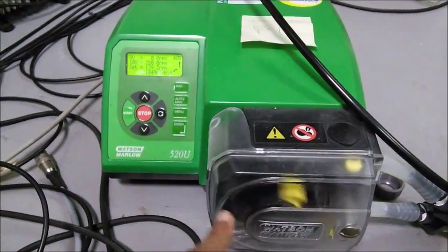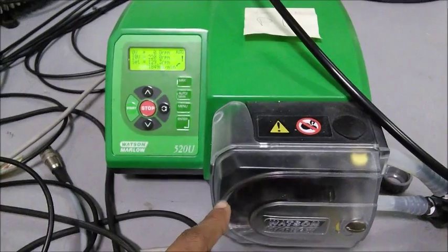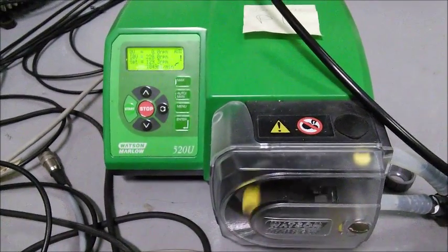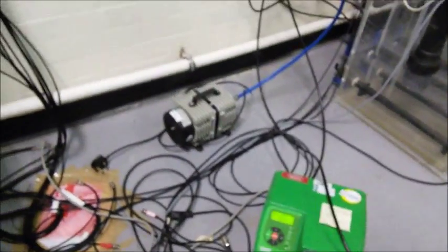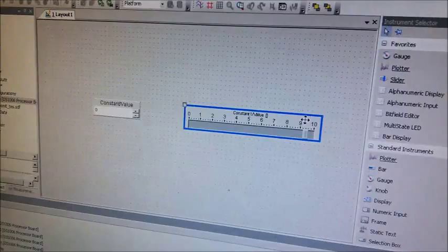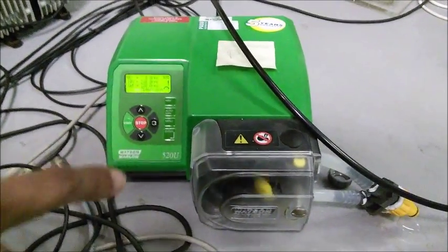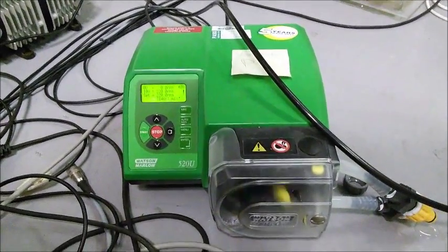And into a clockwise direction, if you want to increase the speed, you can do the same by increasing the voltage here from 5 to 10. So into a clockwise direction, it is changing the speed. So as you have seen how to send a signal to the pump and how to run the pump in a particular direction and speed.